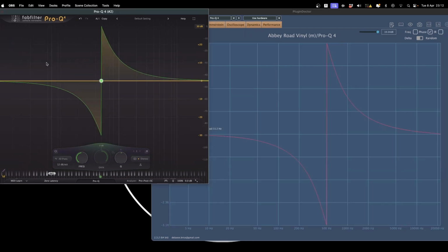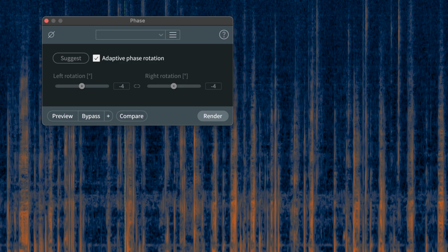So filters and the effect they have on phase will always look back to what has already been made. This is why the shape will also be like this. You couldn't have a shape where it will go up like this, because this would mean that we would go forward in time. We would be in the future before the present time will have happened. And this is one of the specificities of the iZotope RX tool. It can go to the future. It can move things in both directions, while processes that are applied in real time, of course, can't.